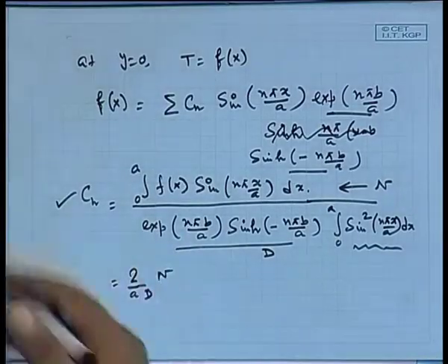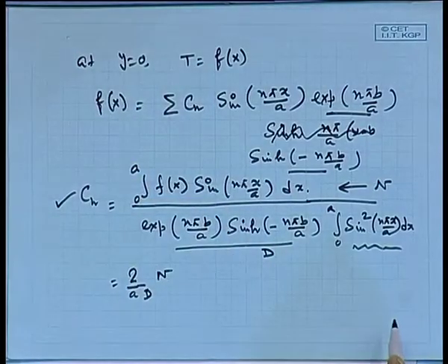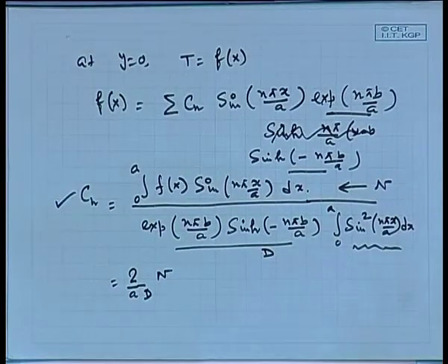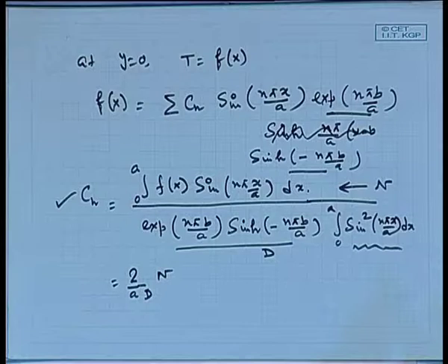So, you can get the complete solution once you put the solution. Again, you see that whenever you will be computing the temperature profile at any x y location, let us say you are having a 3-dimensional plot of t as a function of x and y, you will be seeing beyond 5 or 6 eigenvalues, the contributions of various terms will be negligible towards the whole solution. So, the summation will be evaluated maybe for the first 5 or 6 eigenvalues and you will be getting the solution.